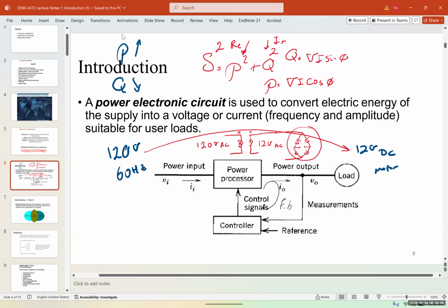So if this is turning a DC motor, and the DC motor is a servo motor or a step motor, and you want to keep the torque, once you apply a load on the motor, the voltage drops, and you're going to have changes in the voltage and the current. That's not desirable. So what we usually do is have a feedback system that goes through a control system that would manipulate the input and output voltage. So there we can increase the voltage.